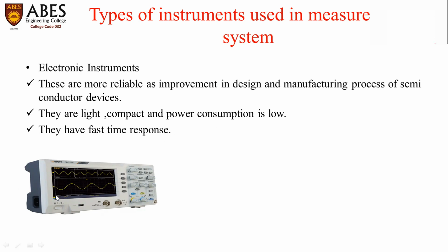So generally we go for a DSO just to analyze the waveform of voltage and current, to measure the phase shifting, and to measure the frequency, time period, and duty cycle. All these things can be easily done with the help of the DSO, in the pictorial representation, in the waveform analysis.